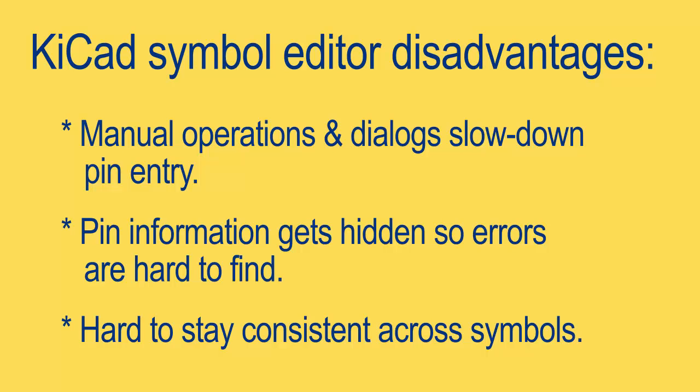Now here are the main disadvantages I see with the KiCad symbol editor. Number one is all the manual operations and the dialogues that are popping in and out slow down the entry of pin data. Plus, some of the pin information gets hidden, so errors are hard to find. For instance, it can be hard to find if you have assigned the wrong type to a pin. You have to open the pin up and take a look. And finally, it's hard to stay consistent across symbols to make all the symbols in your library kind of look the same, and that can be really important if you're anal retentive.